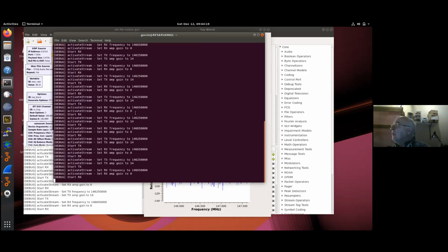David says, do you use a 2-meter bandpass filter in the transmit RF? Absolutely. After the power amp, there is a filter. It's a pi-shaped filter, and from there it goes into the relay. Dennis, DL9CAT, same question. Do you use filters? Yes, I do. Okay, any other questions?